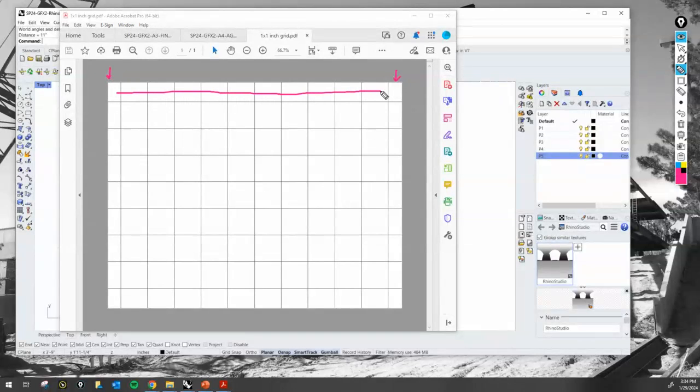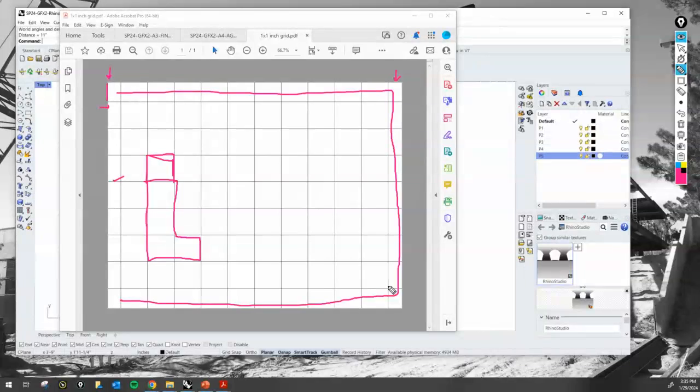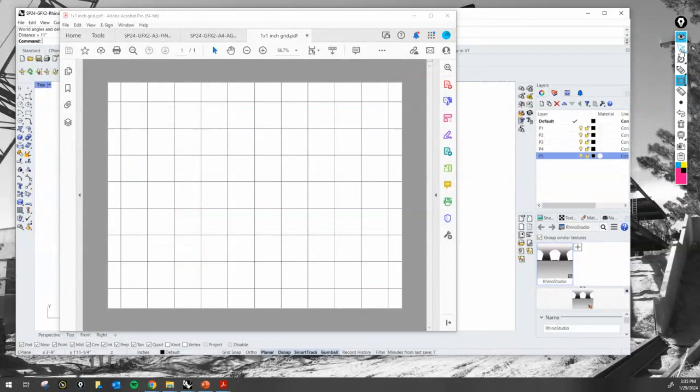The reason for that is I wanted to make sure that we had this margin, or something acting as a margin, so that you can use the inside of this right here to actually draw your work. The reason for that is, number one, the printer is never going to print all the way to the end right here. The printer by design has a very, very small margin, and that can make your layouts wrong. So that's why I wanted us to work all inside of this margin right here. So basically that's what I first want to show you guys how to do.